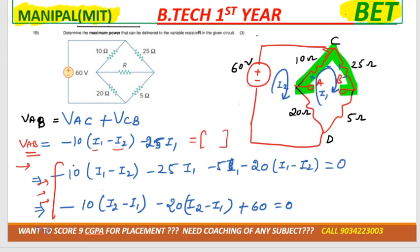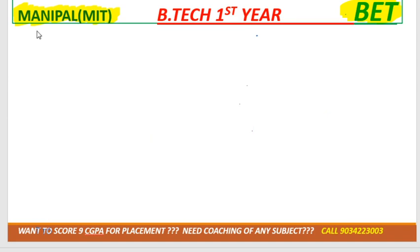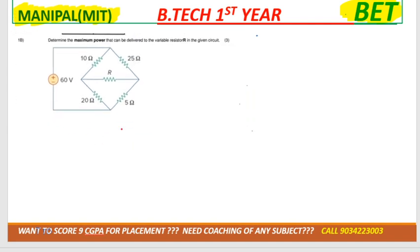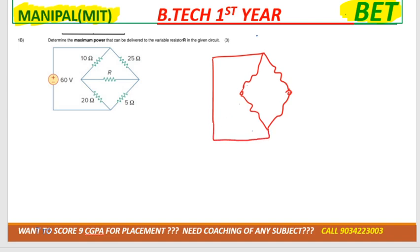I'll check it. Okay. Now in the further steps, you need to calculate RTH, right? So for RTH, the voltage source must be short circuit, the current source must be open circuit, right? In this there is no current source, so I'm making the voltage source a short circuit, and RL would be open circuit.